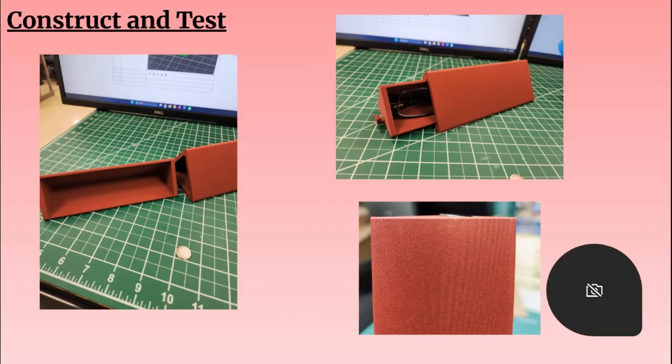The very next day, I took the pieces out of the 3D printer and removed the tree supports. I tried inserting the case magnet inside the hole in the back, but it just couldn't go in. The hole I made for the magnet was already super tight because of its small tolerance, but the tree residue present in the hole made it practically impossible for the magnet to go in. The picture on the bottom right shows you how the magnet sticks out, incapable of fitting inside the hole. No matter how hard I tried with pliers, I couldn't get the residue out of the hole.